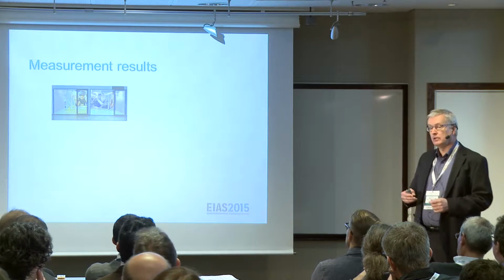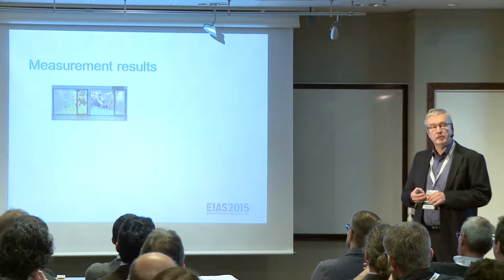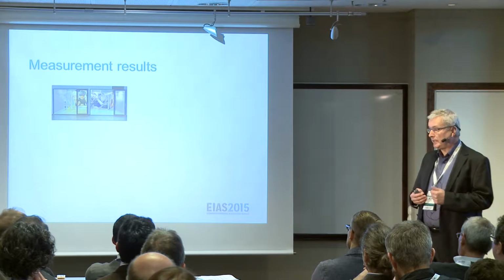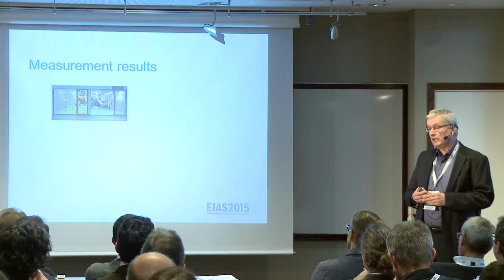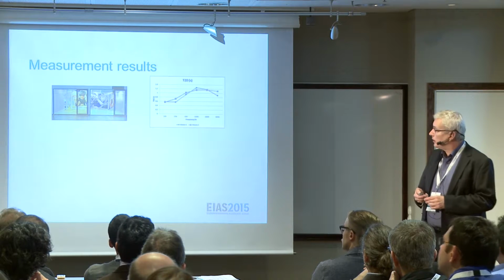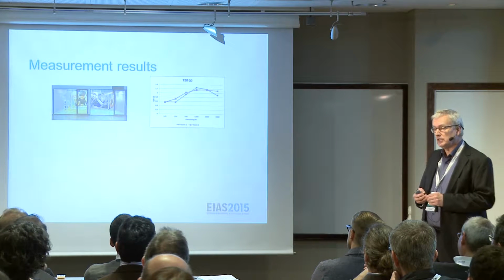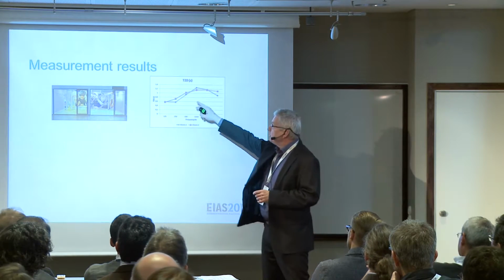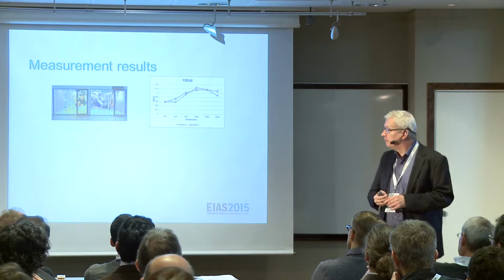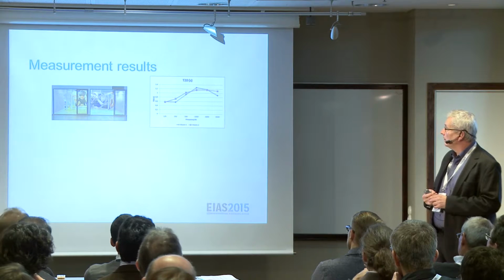Then we did some typical room acoustical measurements in these 2 rooms. We measured the impulse responses, and we calculated the reverberation time, and also the speech clarity and the sound pressure level in the rooms. When we look at the reverberation time, we got this figure, which might be a little bit surprising. As an acoustician, you might expect differences, and there are some differences at some frequencies, but they are quite similar. That's a bit of a surprise, but that's what happened.